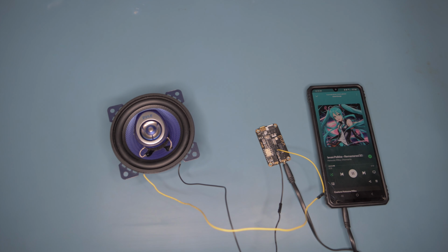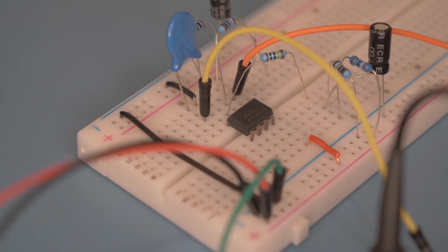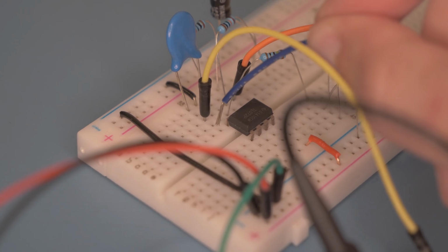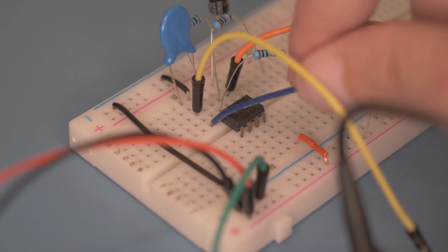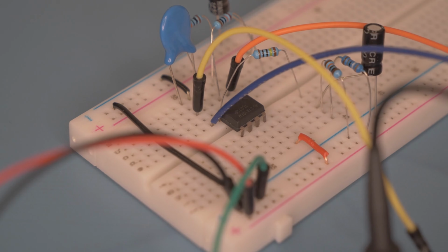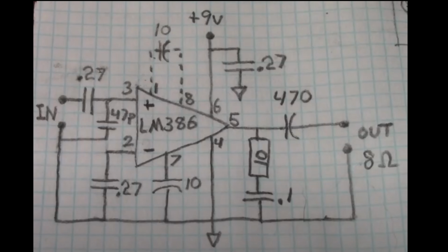Next, I need to introduce an op-amp so that we can amplify the sound and add volume control. In my previous video, I used a generic op-amp, but this time around I ordered 3 different op-amp ICs that are specifically designed for amplifying audio like this. The first I'm going to show is the LM386. The 386 is an old IC, but it's perfectly fine for small applications and hobby projects like this, because it's simple and cheap. While looking up information on the LM386, I found a video that recommended using this circuit.